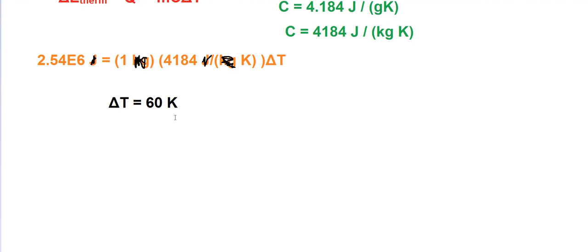So what that typically means is when you're heating things up with electromagnetic radiation only, it's not very good. Contact is a much better way of transferring thermal energy than mediating it through light. In fact, the only time it actually becomes comparable is if you're dealing with something that is ludicrously hot. So the sun is pretty decent at transferring energy via light, but the sun has a temperature that is significantly higher than most of the things that we use on Earth's surface. So basically, if you want to heat something up quickly, instead of just shining a light bulb on it, it's actually faster to take your hot light bulb and push it directly into whatever you're dealing with, or mediate it with oil, water, or air.